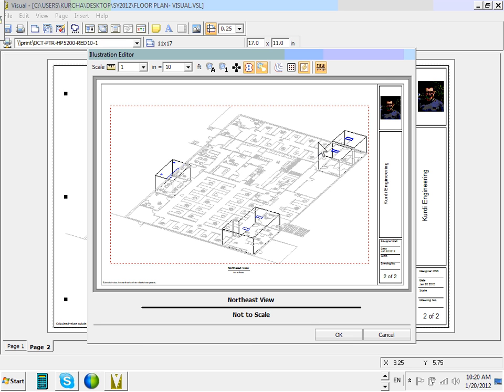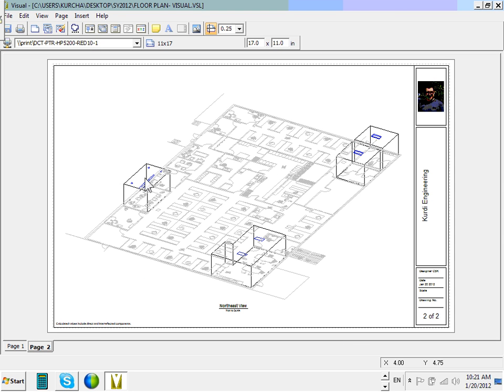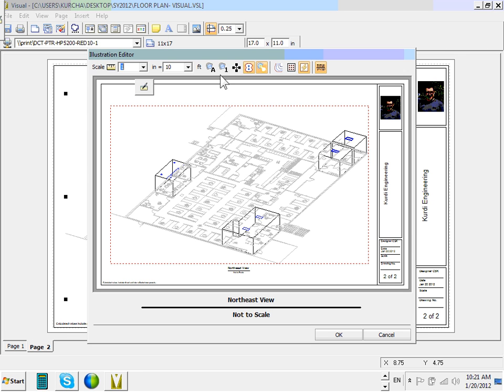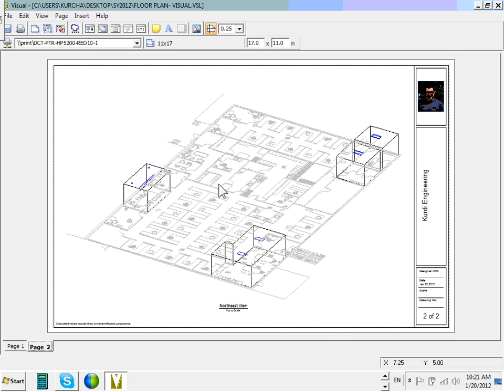Now label. Can you guys see the labels are still there on the 3D image? I might not be interested. Well, I guess we can leave the labels too. But if you're not interested in the labels, here's what your 3D image should look like. The question was, do I want the labels on the 3D image? No. So why don't we double click on it again? Do you guys see where the label is? Unclick the label in my case, and OK it. And you should have a 3D image with no labels and no calculation, just fixtures and 3D.